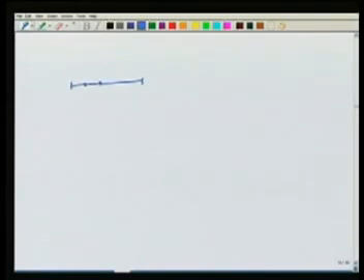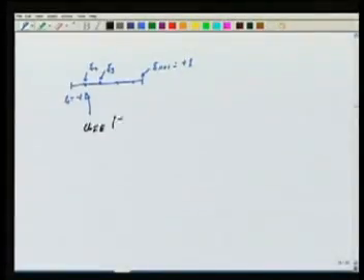Now as far as plotting is concerned, what we can do is take the master element, divide it into some number of subdivisions. So I say psi 1 is equal to minus 1, this is my psi 2, psi 3, so on. This becomes psi n plus 1 is equal to plus 1. I can find the size. At these points I will find the solution. How? By calling the shape function routine, telling it to give me the shape functions and the derivatives, and using that to construct UFE at the point psi i.